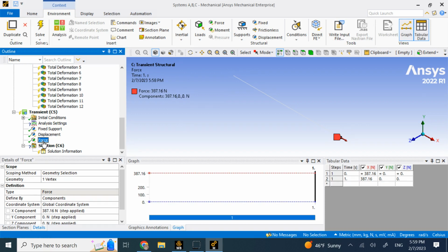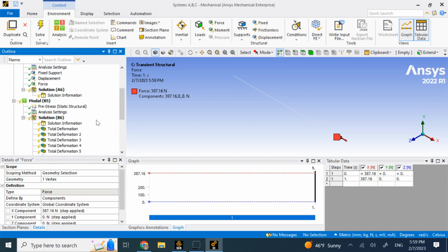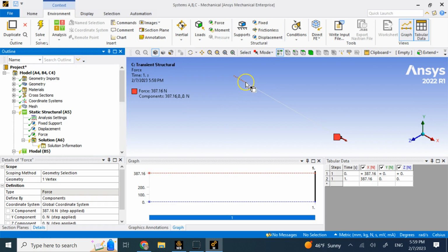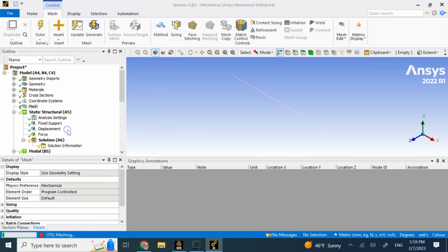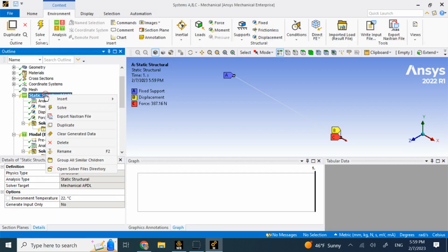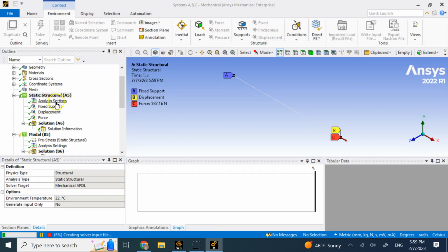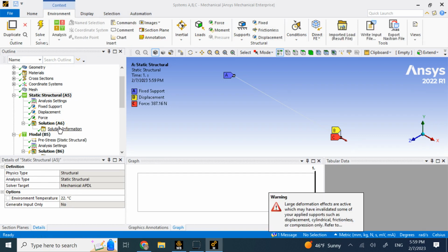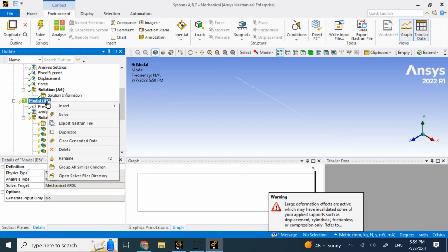The next thing you want to do is, since I broke the string into 8 pieces, you want to regenerate the mesh and you want to redo the modal analysis, right? So here the mesh is done. The static structural, if it's not completed, you are going to go ahead and complete it for now, as well as the modal.